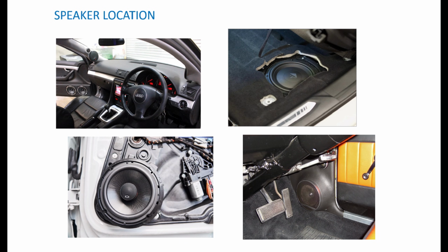Now one of the things that people might do is build up a speaker ring. You just have to be careful that you don't create almost like a tube effect and color the sound, because the back wave or the front wave is making its way through a big tube. So it's one of the things to consider when you're thinking about mounting your speakers in the door cards in what I would term free air. That means mounting it on a ring and having the speaker vent into the void inside the door card itself, right? And then of course there are kicks.